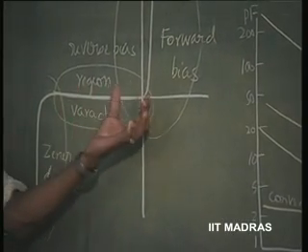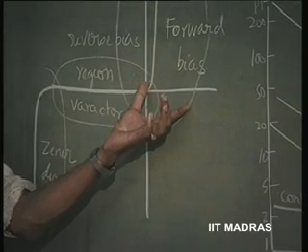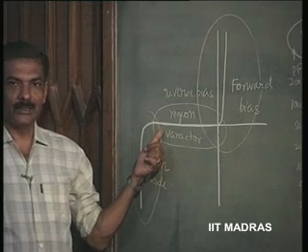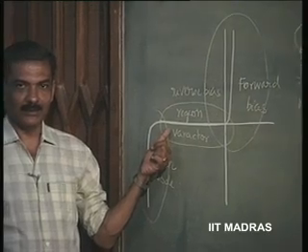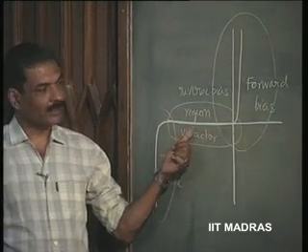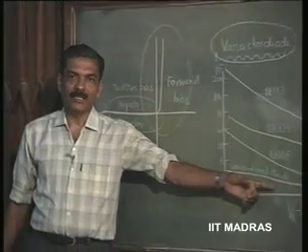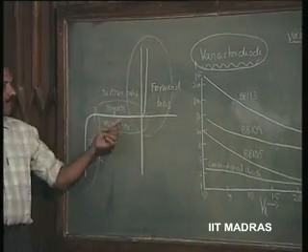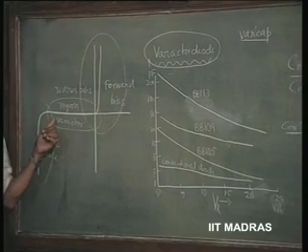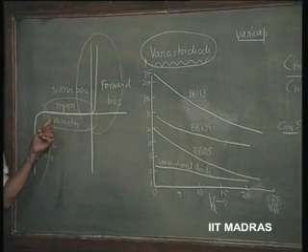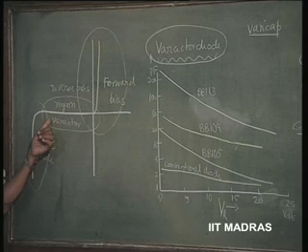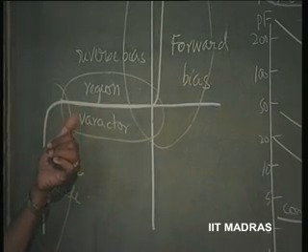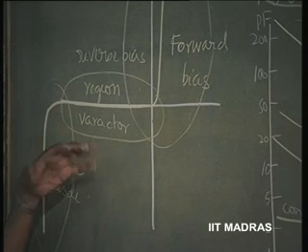So, in the case of a rectifier diode, we are not so much bothered about its use in the reverse bias region where the resistance is infinity. There is going to be capacitance, but its variation is not going to be much. This is the conventional diode. So, if it is a power diode, the area is going to be larger and the capacitance also is going to be higher. If it is a small signal diode, the area is going to be smaller and therefore, the capacitance is going to be lower.